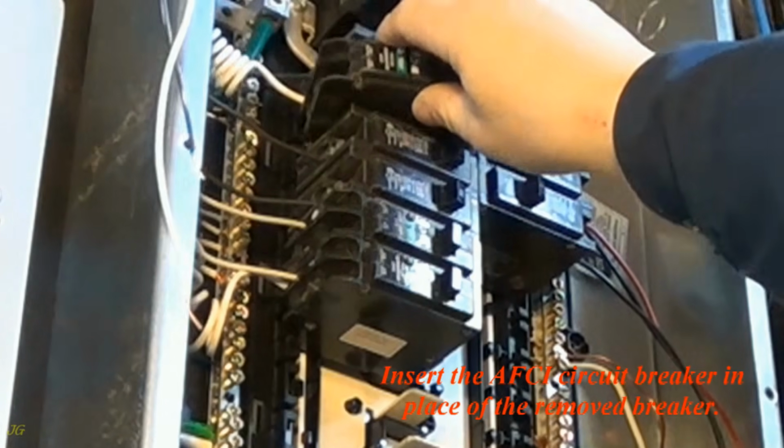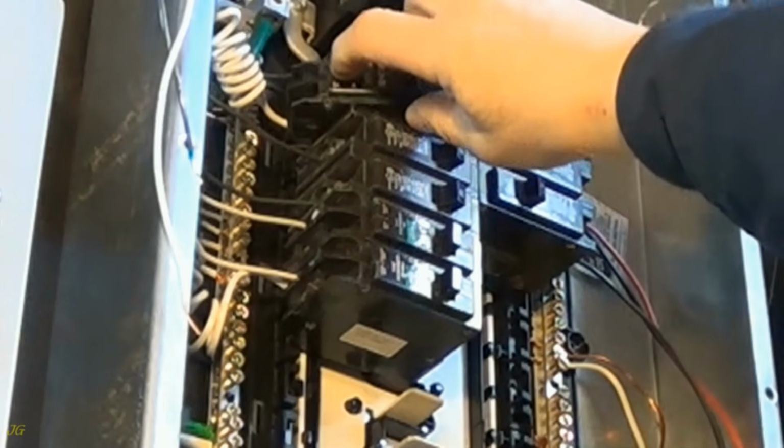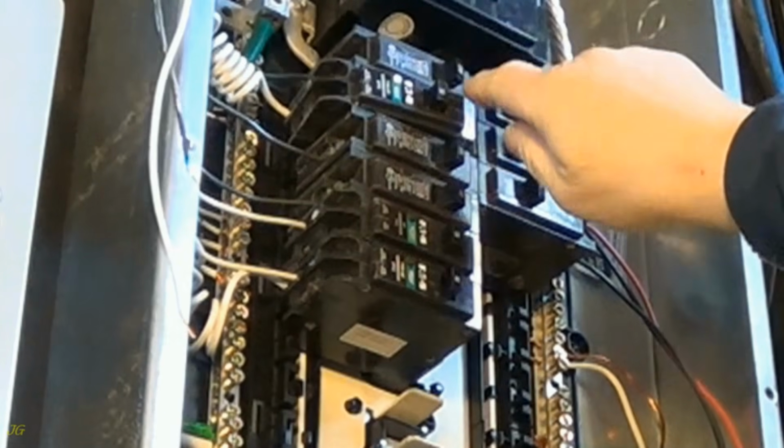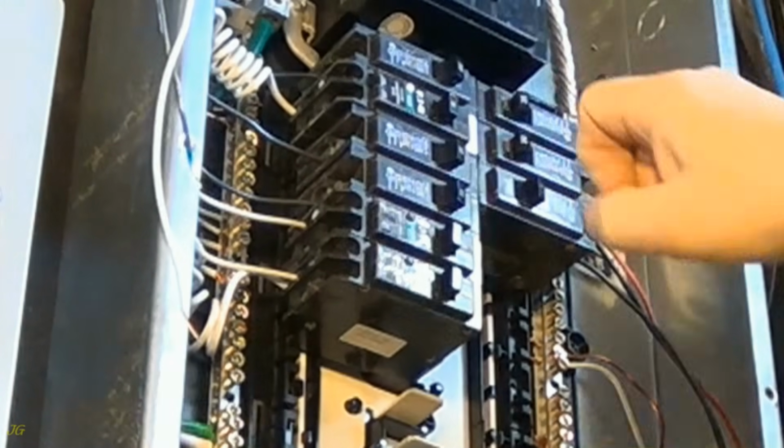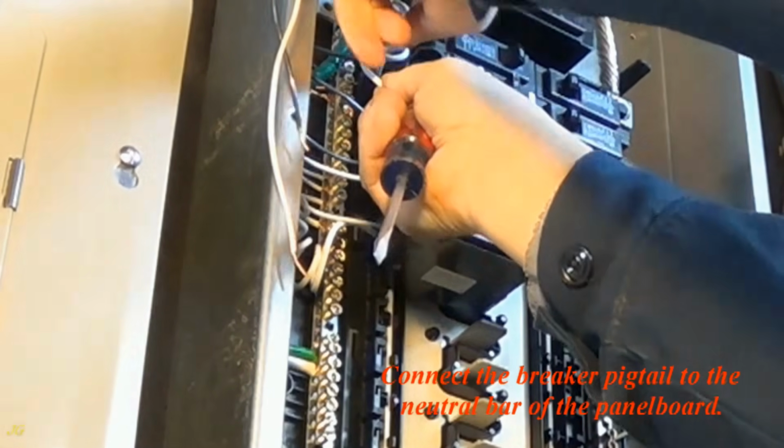Insert the AFCI circuit breaker in place of the removed breaker. Connect the breaker pigtail to the neutral bar of the panel board.